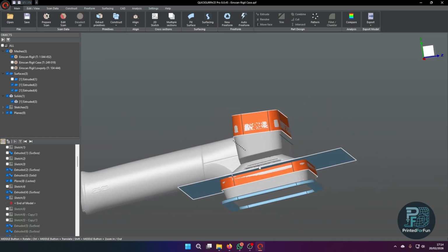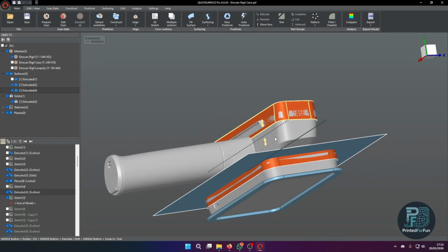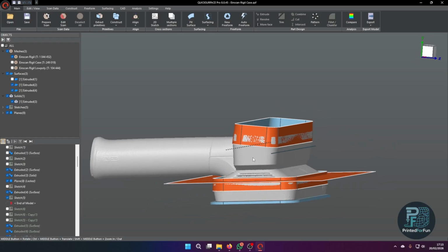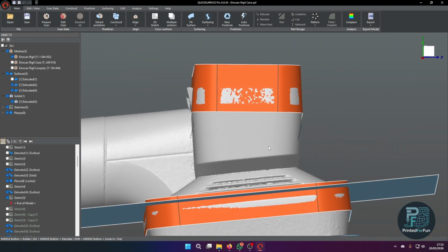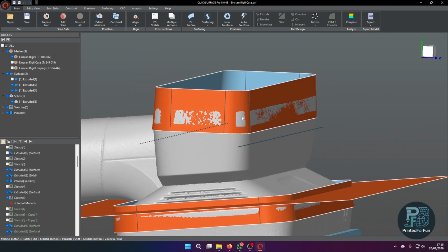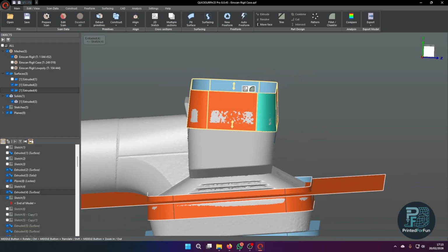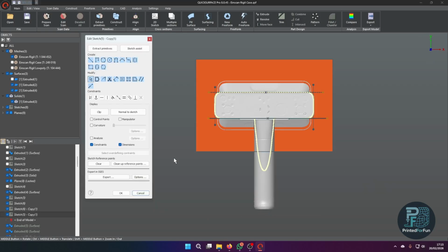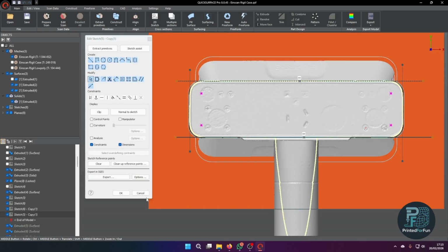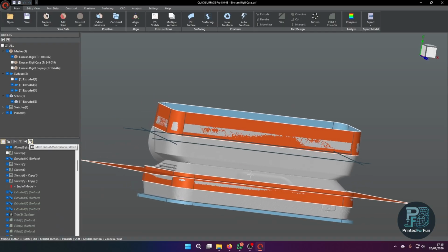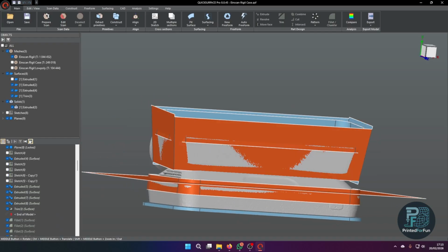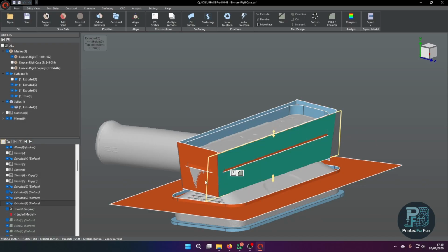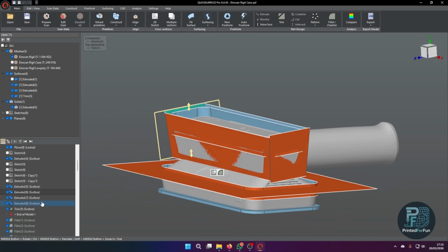So now I can start with this draft surface, and sadly it's not draftable as one intersection, so it cannot be done like this, but I have to create 4 sketches, and on each sketch I extract one side of the intersection. Now I can extrude all 4 of these sides, and in the next step use a trim operation to create one envelope.